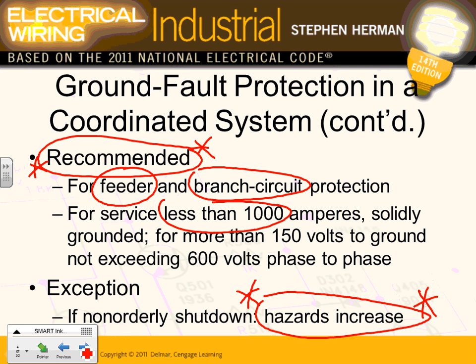In any area that will cover sensitive chemical and manufacturing equipment that you cannot interrupt because of a ground fault trip, I don't care if there's a ground fault. Interrupting the process will create more hazard than having a ground fault. Does that make sense? Industrial applications.